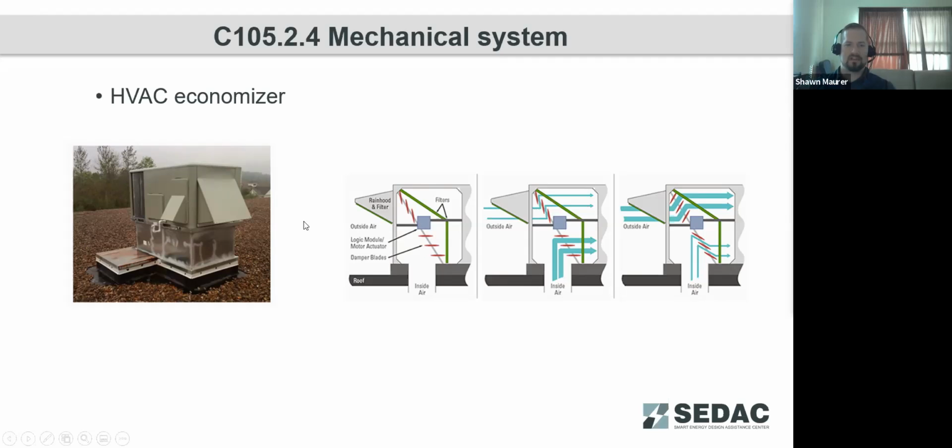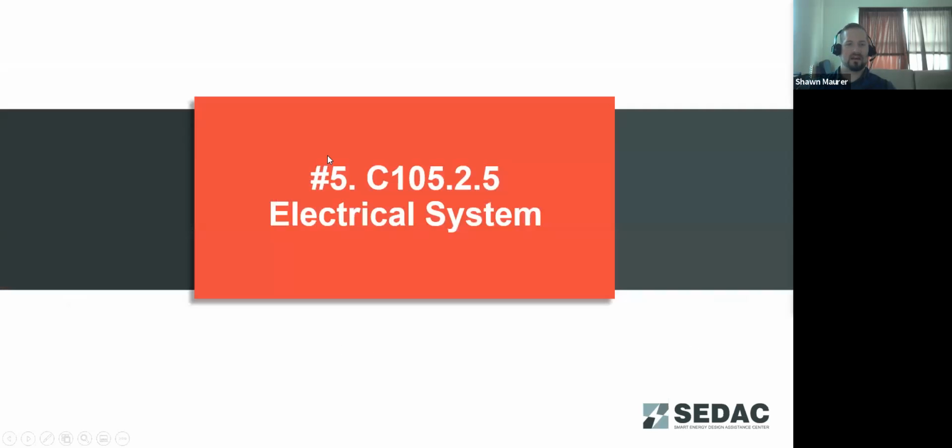HVAC economizers, are they working properly? Do the dampers have full range of motion? Are the set points correct for the climate zone that you're in? All important considerations for economizing systems.